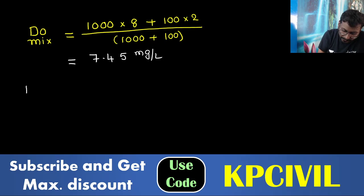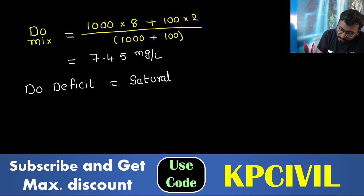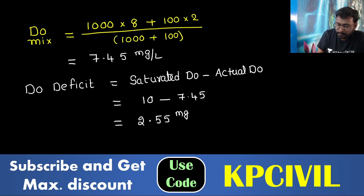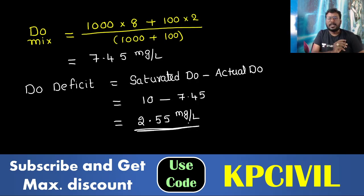But the question is about DO deficit. What is the formula for DO deficit? Saturated DO minus available DO. Saturated DO minus actual. Actual is available, actual DO. Saturated DO is given 10. Actually, according to mix phenomena, we got 7.45. So what is DO deficit? 2.55 mg per liter. DO deficit is considered as 2.55 mg per liter.